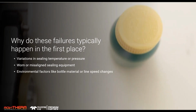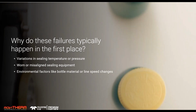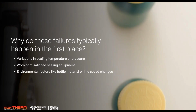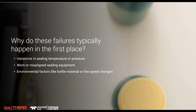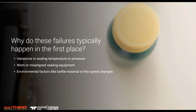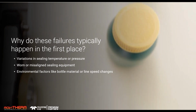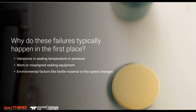Inconsistent line speeds. Maybe you have a defective liner in the cap. It could be from improper torquing on the torquer. That could really change the thermal signature by that pressure change. You also have the overheating, underheating issues, or maybe the bottles when they're coming down the conveyor are slightly misaligned, which can create a defect. Incompatible caps or bottle materials from different molds can have an effect, or maybe it's just human error that they put the wrong setting in.